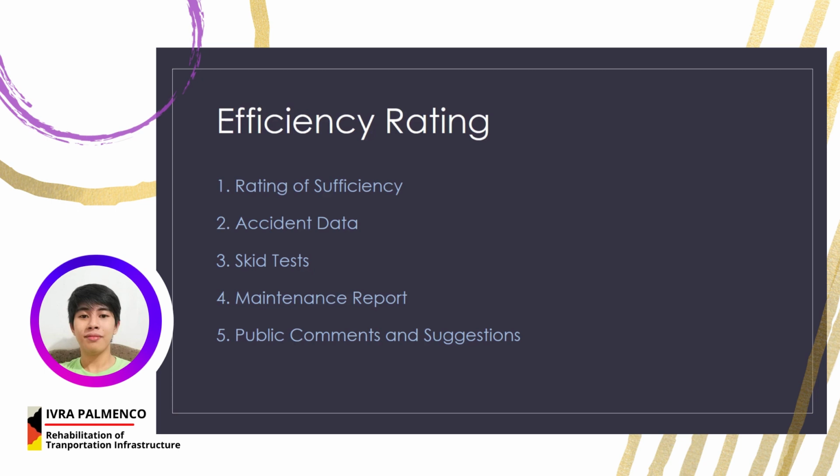Then we have skid tests. The device used in skid tests measures the frictional resistance between a rubber slider mounted on the end of a pendulum arm and the surface to be tested. This provides road engineers with a method of checking the resistance of wet and dry surfaces to slipping and skidding, both in the lab and in situ, helping to prevent unnecessary accidents that may occur due to slippage.